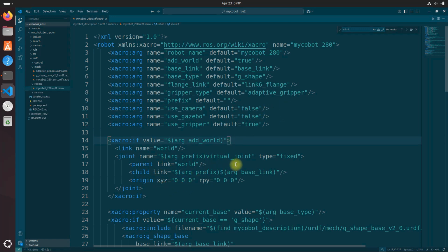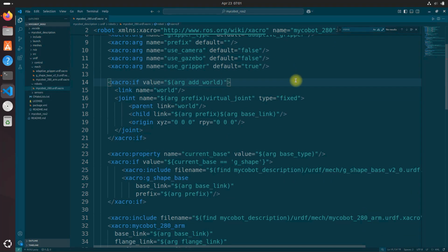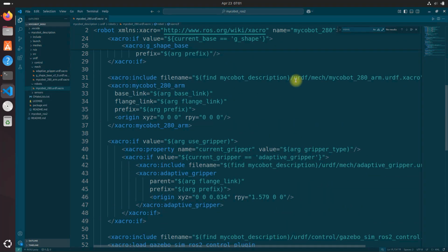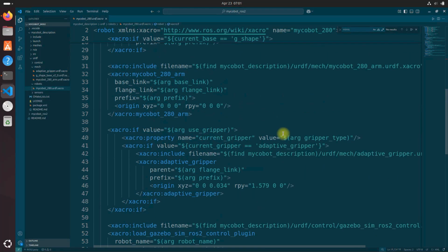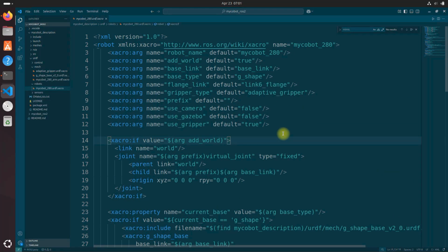We've covered everything from declaring the robot model, defining the links, defining the joints, setting up the properties, the mimics. So XACRO files, please don't be intimidated. They look complex the first time you see one. I remember the first time I saw one, I was like, oh my gosh, this looks like Greek hieroglyphics. I'm scared. But don't. Just break it down into small pieces.